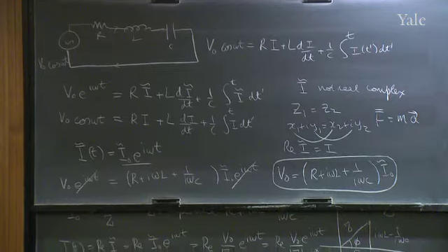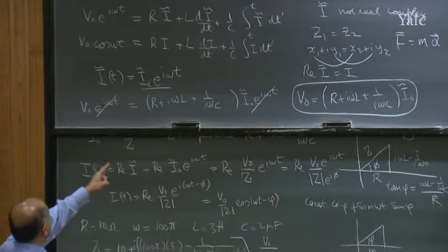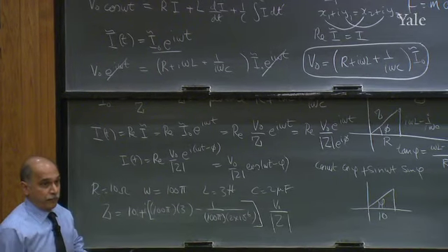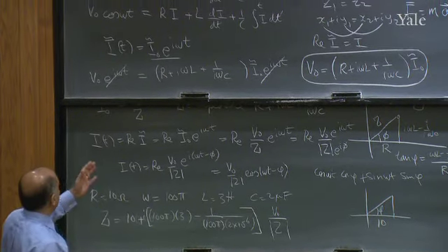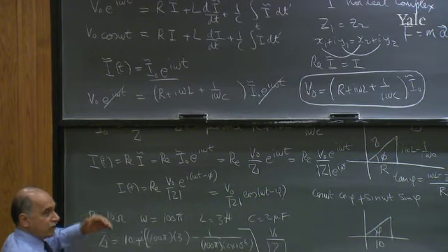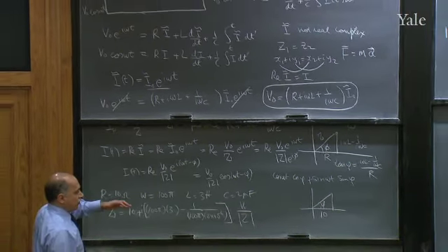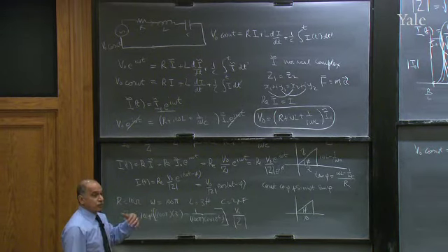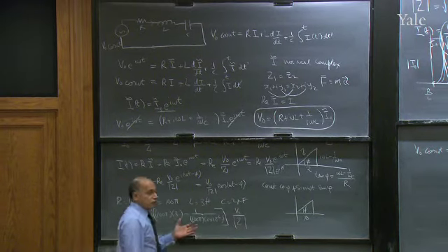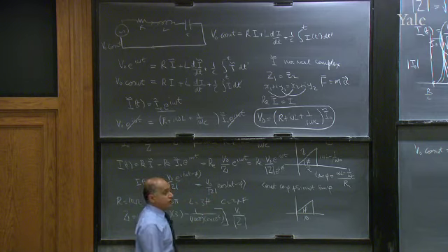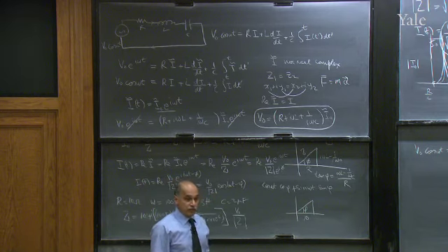It all comes because there's nothing non-linear. For example, if the right-hand side had R times I square, then the first equation will have R times I1 square. Second will have R times I2 square. When you add them, you will get R times (I1 square plus I2 square). But what you want is really R times (I1 plus I2), the whole thing square. So if you have nonlinear terms, you cannot add solutions. But if you have linear terms, you can add solutions. Therefore, 0 is a hint. It says add the solution for 0 voltage.